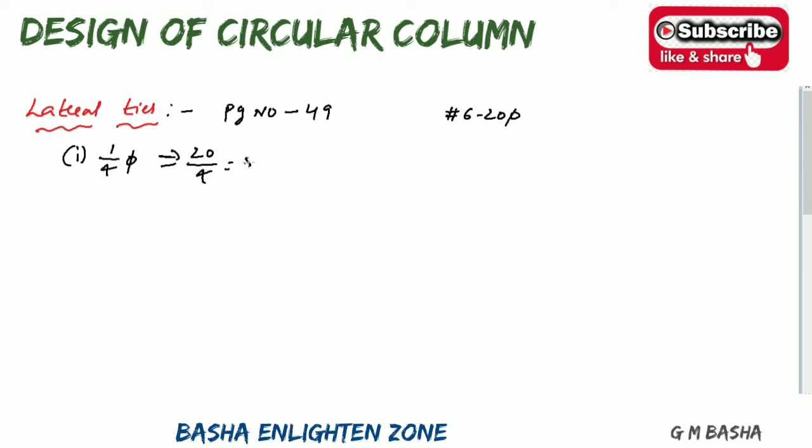20/4 will be equal to 5 mm. Another condition is that it should not be less than 6 mm. Out of these two values, based on the first condition you get 5 mm, and from the second condition 6 mm. So the minimum bar we have to choose according to our conditions is 6 mm.